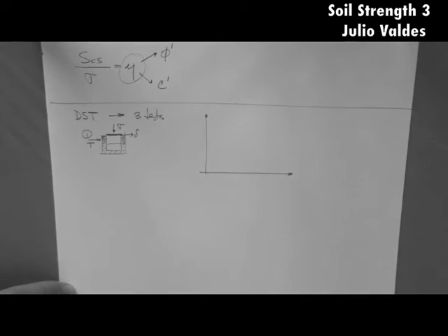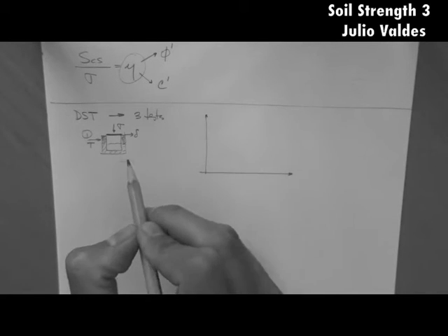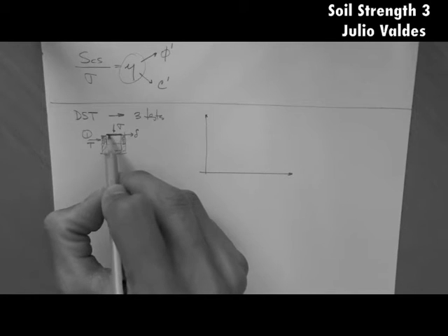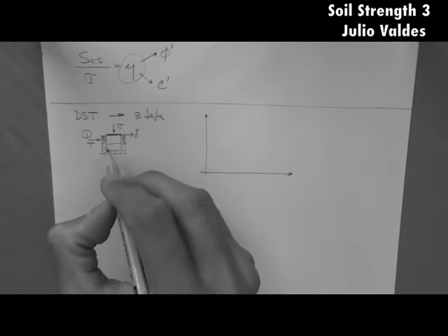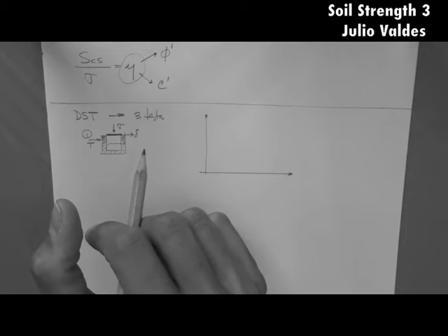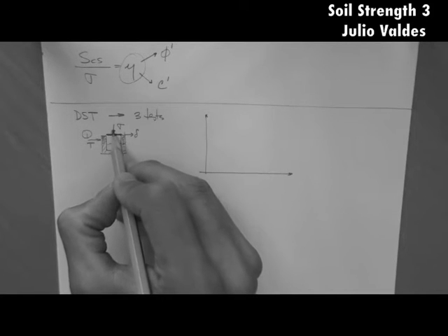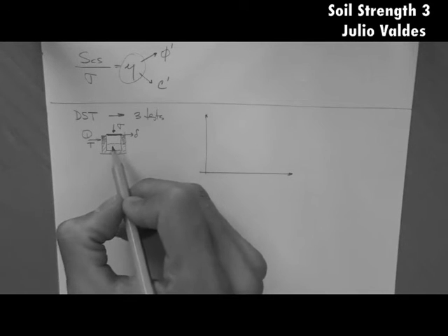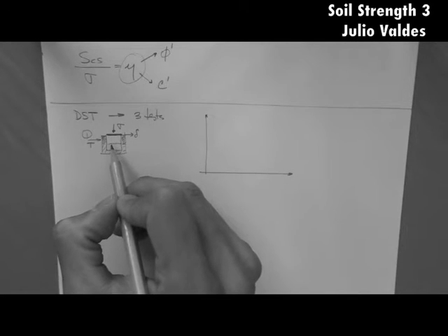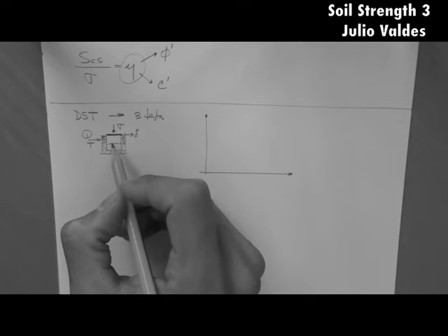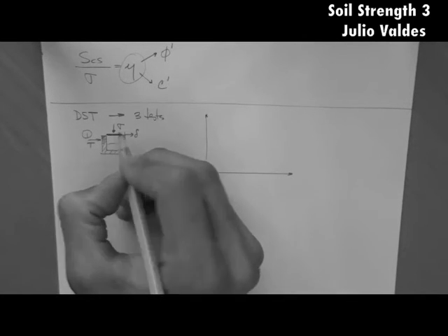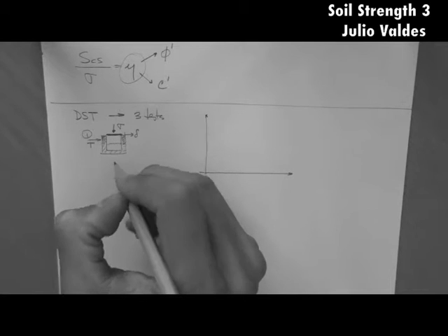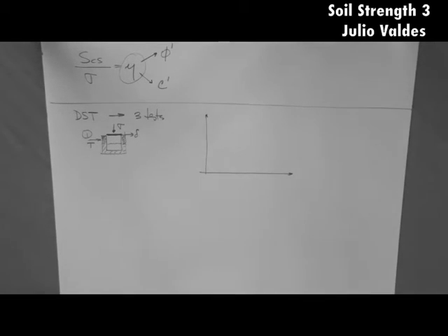Now, important. When you apply a weight here, or impose a weight, who takes the load? Meaning in the soil, the water or the grains. Remember that this whole apparatus is submerged in water, so this soil is saturated. So if you place a load here, a weight for example, the water in the pores is going to carry the load first, and consolidation will then occur so as for the water to transfer the load to the grains, right? So there will be generally a little settlement or deformation, axial deformation of the specimen, of course due to consolidation.